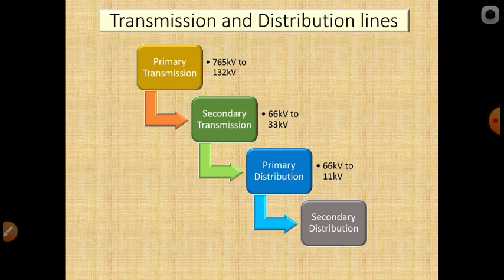At the same time, we also have to consider frequency, plus or minus 5%. The Indian frequency is 50 Hz, and plus or minus 5% means 2.5 Hz. So a frequency of 47.5 Hz to 52.5 Hz may be supplied to the consumer. That is the main aim.